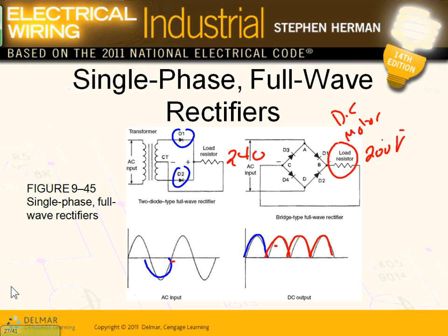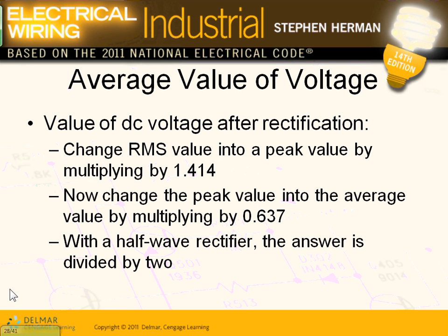And today is not the day of talking about the diodes biasing and so forth. To calculate, take this first. You take an RMS value. Let's do an example for 480. I have a 480 RMS value that I need to convert to a DC. The first thing you do is multiply it by this number. Chris, help me with this, please. 1.414. You multiply it by square root of 2 to find the peak.